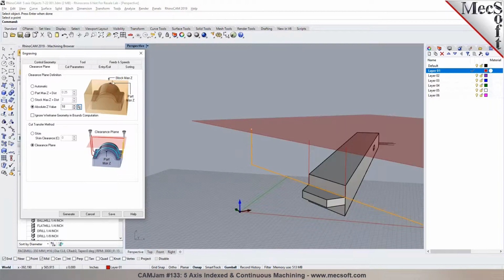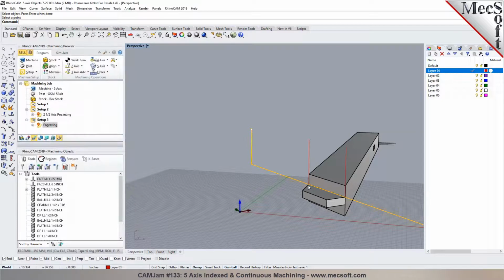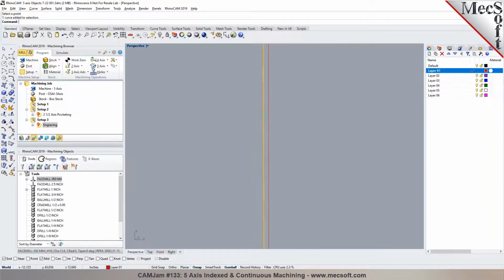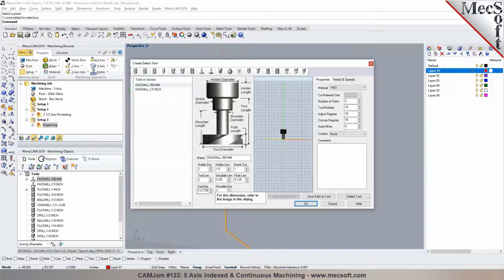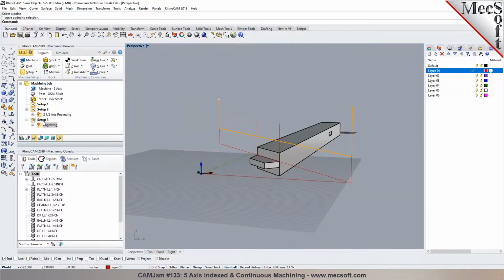Okay. And the cutting, I don't need to put in any depth in here unless you want to go in multiple steps. Also, I would want to offset it out by the tool radius up in the Z. This is the center of the tool that's going to be in here. So if it's going to be the tool center, I want to make sure that this is offset by half of this distance in here. So 13.77, so let's say it's about 14. So half that amount is about 7 inches. Mm-hmm. So that's where you want the geometry to be.